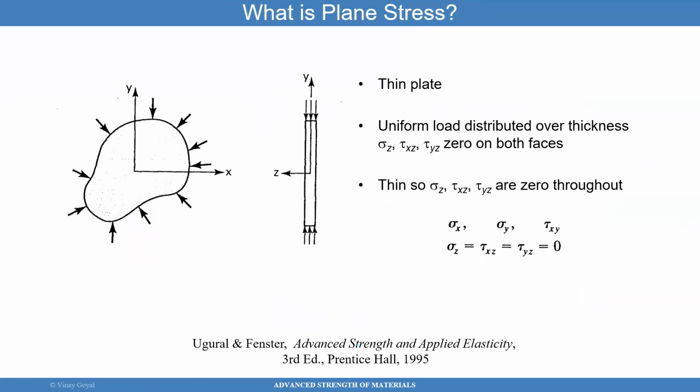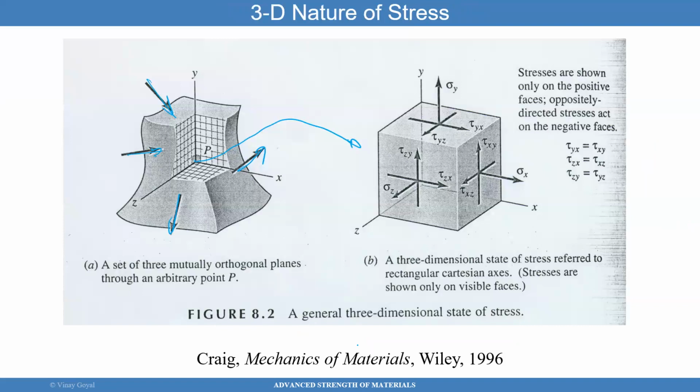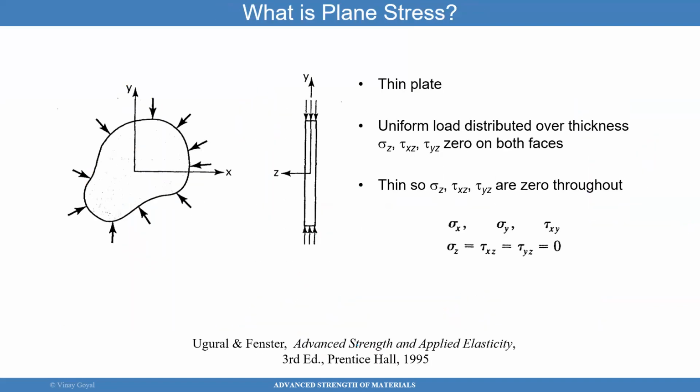But what is plane stress? It's a simplification from the 3D state of stress. So this is true always, but plane stress is a condition. Say you have a thin plate, right? So that's a thin plate here that you see, a very thin plate. H is not exactly 0, but it's close to 0. So it's fairly thin. And all the loads you applied are in the plane that you see there. So they're all in the XY plane. You could have an out of plane loading condition and still trace plane stress, no problem. Just showing you what I'm doing here.